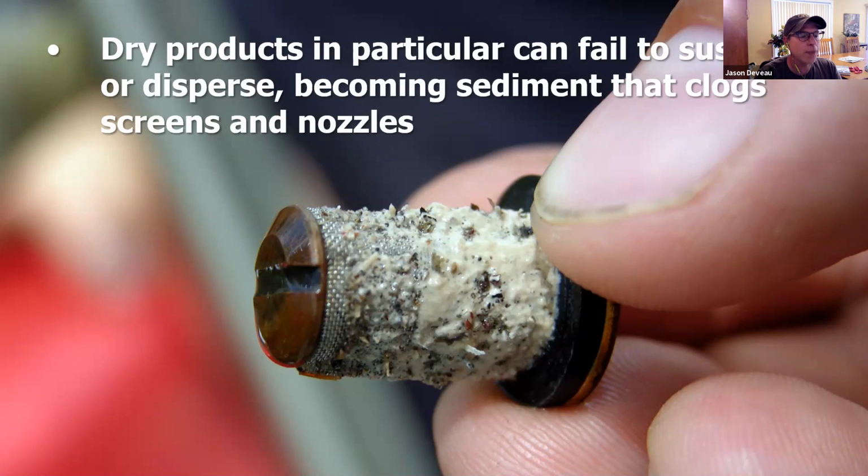So dry products, if they aren't added correctly, can fail to suspend or hydrate. They can fail to disperse, and just imagine little fireworks. The granulars go in, liquid hits them, and they just sort of explode. And when they do that, they're better able to suspend in the water. But if you coat that firework, if you drop them into an oil before they hit the water, they'll never hydrate. They'll just be coated like a chocolate-covered almond, and they'll fall right to the bottom.